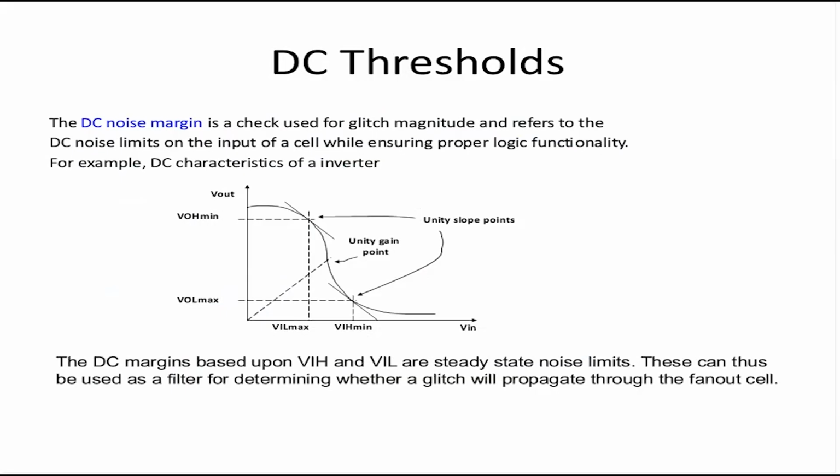So please remember, usually when you work in PrimeTime, when you start analyzing noise, in most cases you will not have to do anything. You just have to enable noise. All this data, the noise thresholds and everything, usually comes from the library itself. The non-linear delay model is only for delay, not for noise.